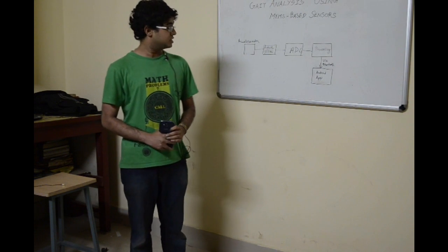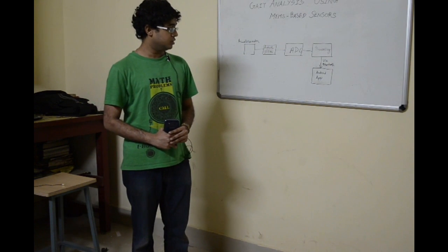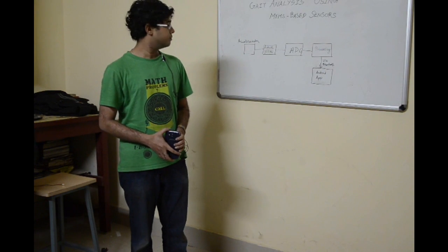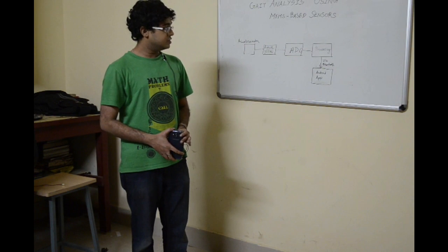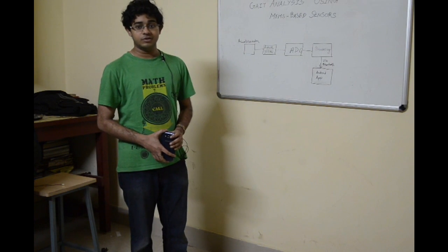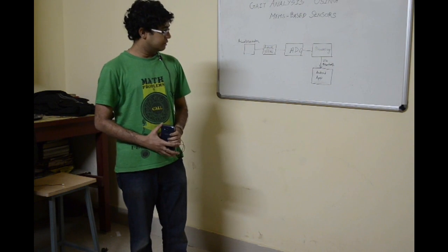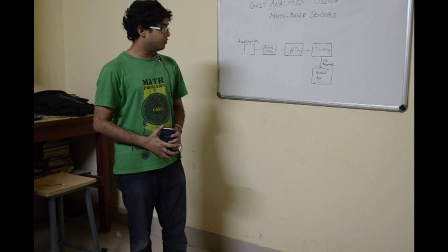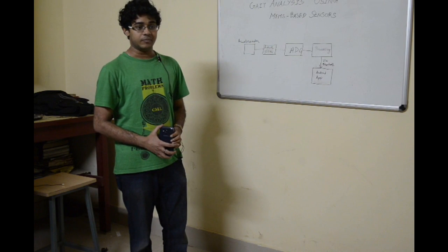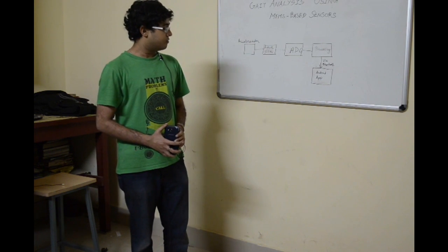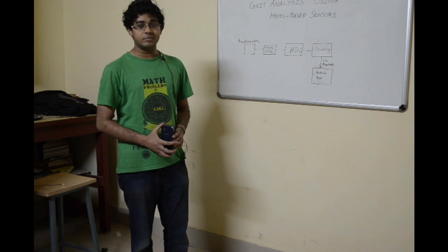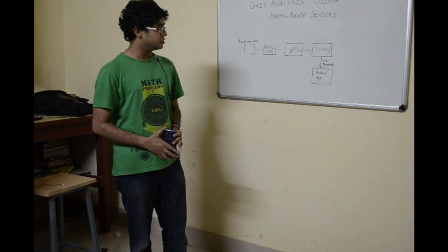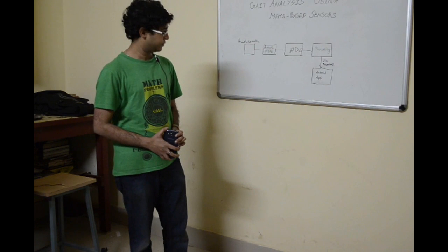This analog data is now passed on to an analog to digital converter. The IC that we have used, ADC 0809, is an 8-bit parallel ADC. This data is sent to the microcontroller boards for further processing. The first board, the Arduino board, is used for acquiring the data and for calculating the local peaks at the minima. While the calculation of peaks can be done for both maxima and minima, for our project we have limited the scope to using only the minima data.